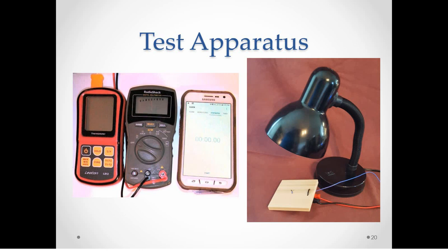The black multimeter lead was plugged into the center port, which is the common ground port labeled COM, and the red lead was plugged into the right port, which is labeled for the measurement of voltage and resistance. To turn on the multimeter, the switch is turned from the off setting to the position labeled with the Greek letter omega, which is the symbol for ohms, the units of resistance. And finally, I'll be using the stopwatch on my cell phone to measure time.